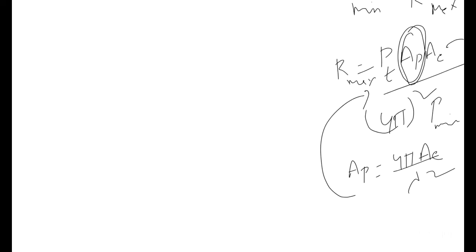From the radio frequency amplifier, what signal are we getting? Vs equal to capital Vs sin omega s t. From the local oscillator I get VL equal to capital VL sin omega L t. These two are multiplied. Output voltage V0 equals Vs into VL. We have one formula: cos C minus cos D equals 2 sin((C plus D)/2) sin((C minus D)/2).